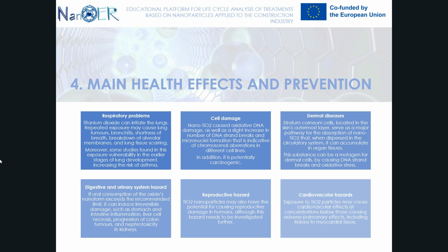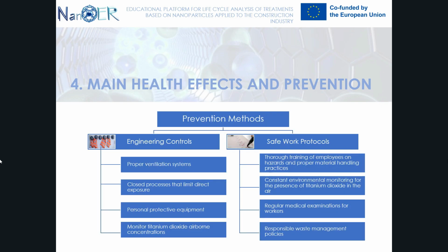As to cardiovascular hazard, exposure to TiO2 particles may cause cardiovascular effects at concentrations below those causing adverse pulmonary effects, including lesions to myocardial tissue. Preventive measures should encompass both engineering controls and safety work protocols. Key engineering controls include implementing proper ventilation systems, utilizing closed processes to minimize direct exposure, ensuring the use of personal protective equipment, and monitoring titanium dioxide airborne concentrations.